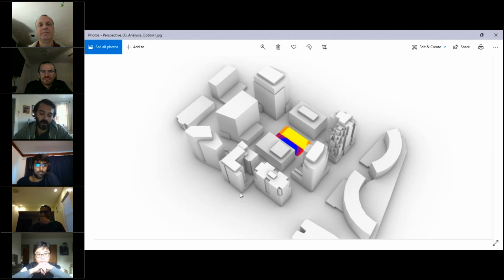This is a script called sunlight hours. It's sort of the inverse of a shadow study in a way, but it will show you in the yellow where you get complete direct sunlight compared to something like the blue, which is sort of the 0 value. So 4 is yellow, 0 is blue. There are, I think, 9 different scenarios that we went through, all changing the proposed designs.